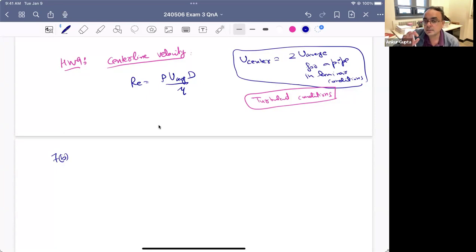We don't have an acceleration in part A because we are looking at the case of maximum velocity. The maximum velocity will come when du/dt is zero. You want to get a maxima. Initially you start with zero, you accelerate, and the drag keeps on increasing. Then at one point, the drag and the propulsion force have balanced each other out. So that's the maximum velocity. In this case, we can also call it the terminal velocity if you want.